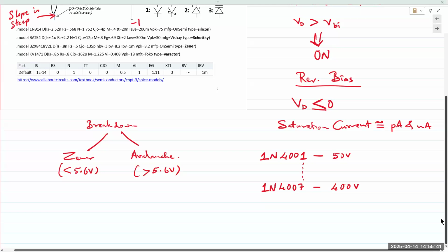They in turn will collide with other atoms, causing more electrons to be generated, which will go further down the chain. It's a cascading effect that must be kind of controlled and stopped at a certain point. So this cascading effect creates an avalanche of carriers to be generated, hence the name avalanche.